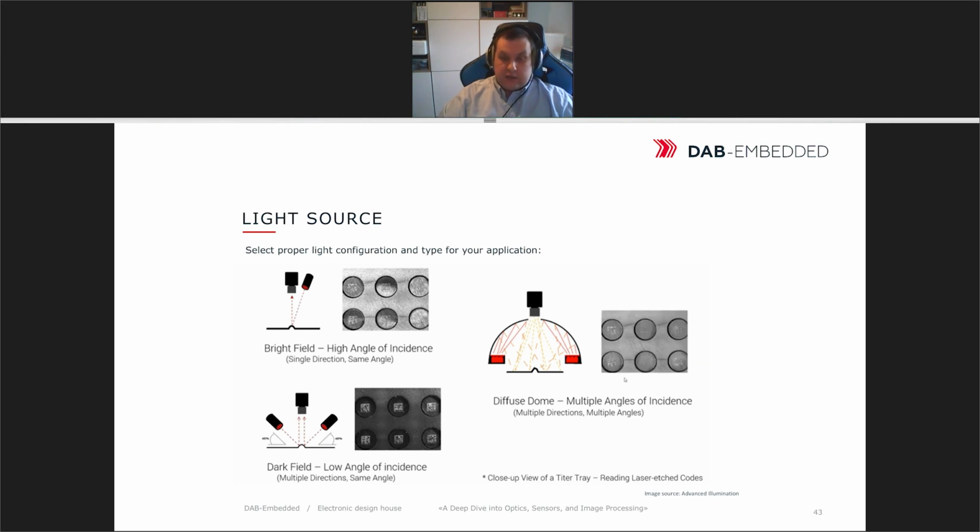There is also an important thing to be careful about when you're working with machine vision, especially when you're using light. We need to be careful about what kind of light we use, the angles, the number of light points, and how it's implemented. So be careful when you select the right light source. You can, of course, experiment, but this is also an important point. If you already see a high level of noise on your camera, you probably need to use a light source.